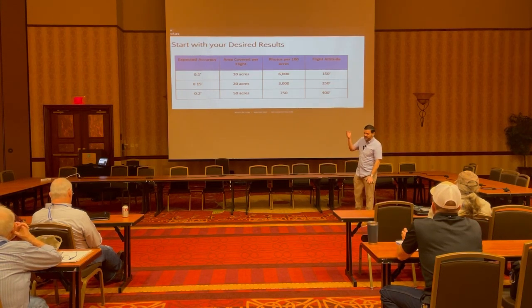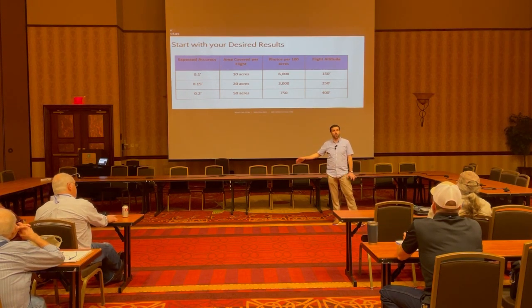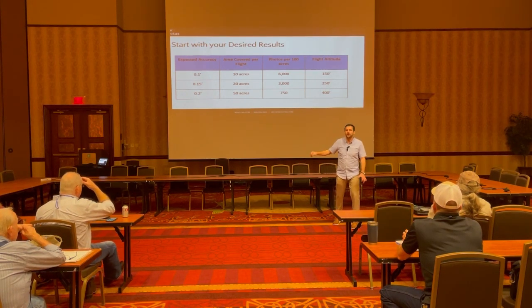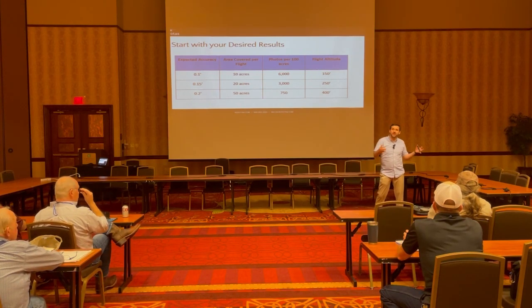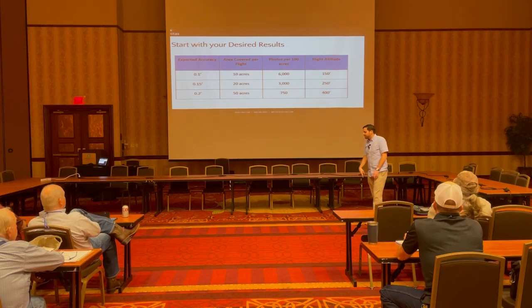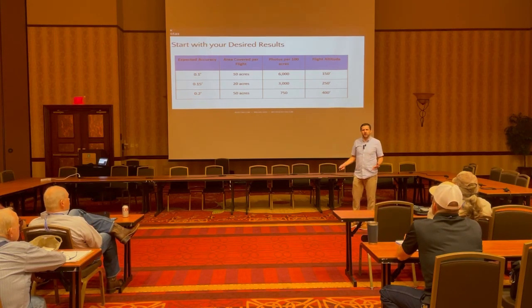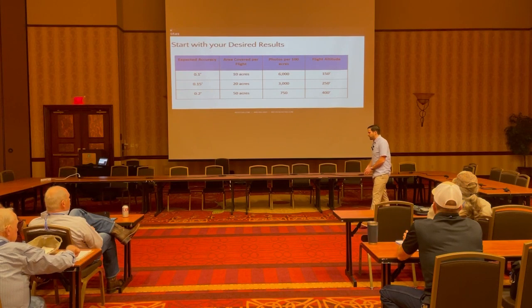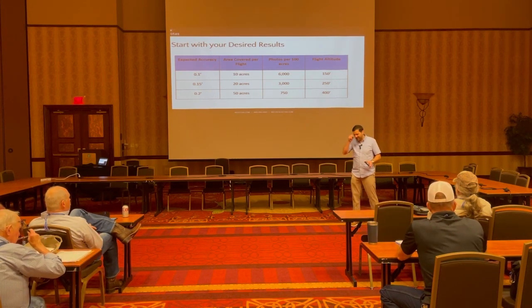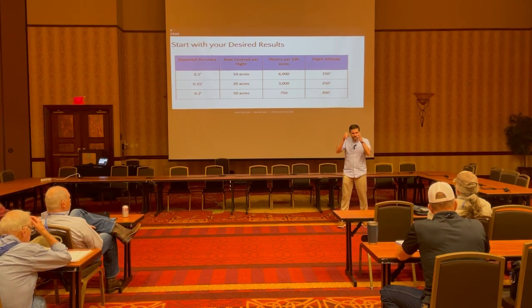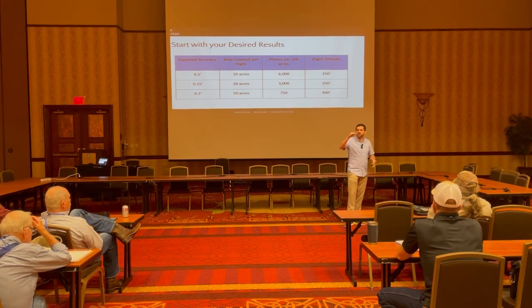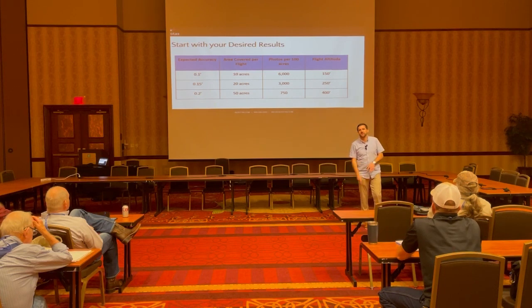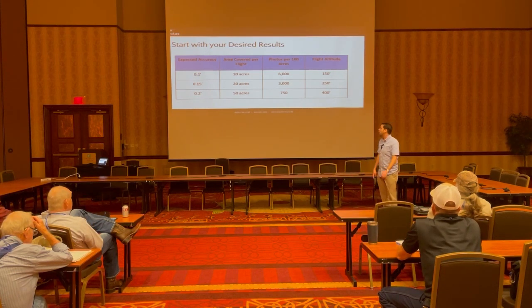So 250 feet is our recommended altitude, just kind of as a baseline. If you're just doing topo 1-foot contours, fly at 400. If you're doing something where you need real detail and a lot of hardscape and utilities, fly at 150. It rarely makes sense to ever fly below 150. Then it starts to suffer from what we call the drinking straw effect. It's like trying to survey through a drinking straw: the footprint that the drone can see is just so small that you actually wind up getting worse accuracy once you start getting lower than 150 feet. So we don't recommend flying below 150 feet.